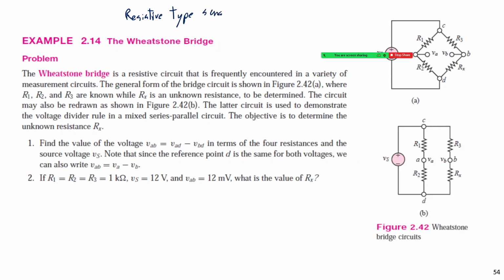It means that the resistance of the element varies due to some parameter, for example, with temperature. If it varies with temperature, we can use it to measure the temperature, right?